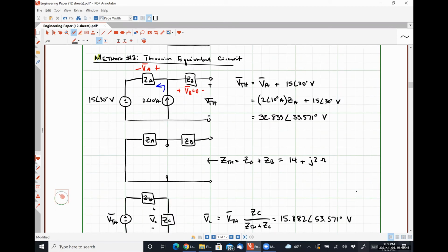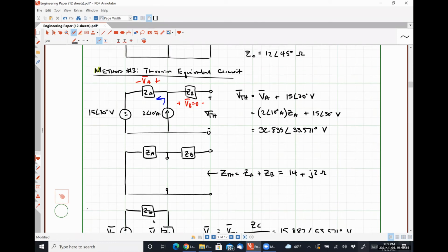If we did a Norton equivalent circuit technique, we're not going to here. What would effectively happen, or one easy way to analyze it, would be, since we're going to have that short circuit on the right-hand side, if we did a source transformation on that practical voltage source and combined those two sources together, we would know our Norton current in 2 steps, because that's all the current that's going to flow through the short circuit. And then we would find the Thevenin equivalent impedance in the same way, and we'd be there practically just as fast. So Norton equivalent circuit would also work here, but I'm not going to bother doing it because it's so similar to what we wound up doing with the source transformation method.